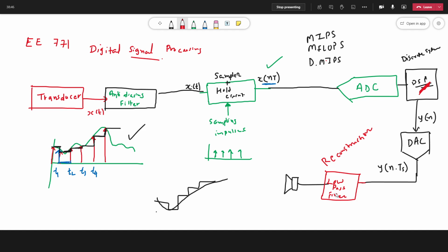The relay will measure the RMS quantity of the current of the relaying signal. So current transformer will serve as a transducer, and secondary output of current transducer will be given to analog to digital converter via certain block we have already discussed. Of course, we still need to discuss about anti-aliasing filter, and we'll be discussing it shortly.